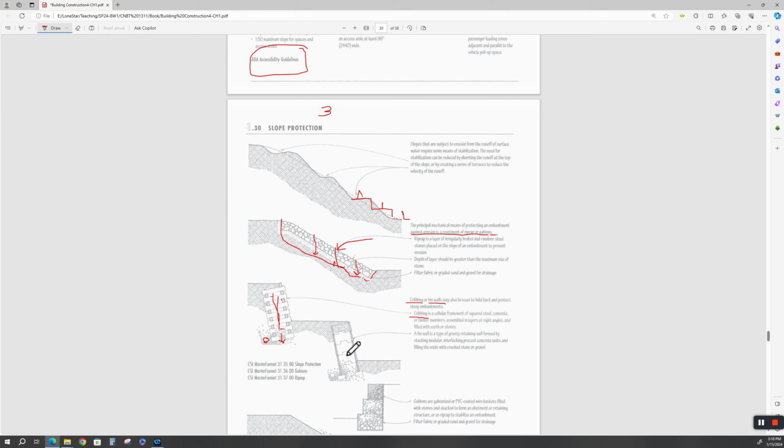This one is a bin wall, a precast bin that basically is heavy blocks of concrete with a keyway. That little notch right there is called a keyway, and it fits in, and you stack. But you'll notice these are on an angle, and they have a foundation underneath here, and you just can't build this like that.